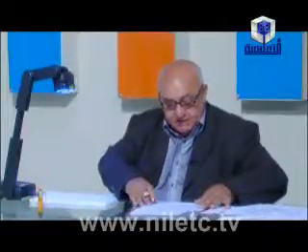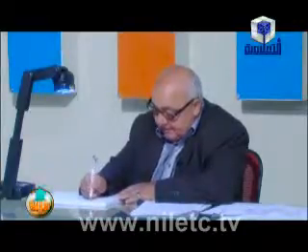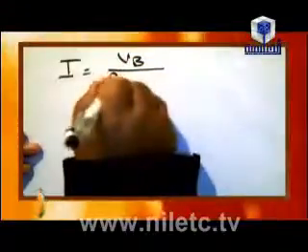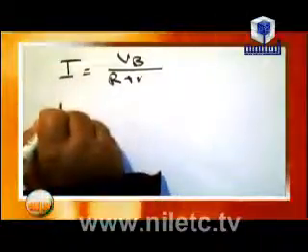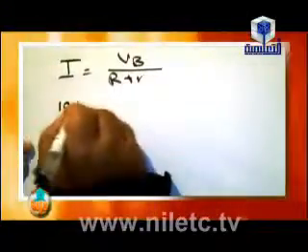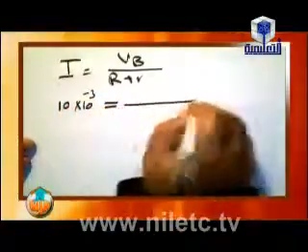After this, we want the value of resistance in order to read 10 milliampere. We apply the rule again. I, the current intensity, equals VB over R plus r. The current intensity is 10 milliampere, 10 times 10 power negative 3 in order to convert it into ampere.